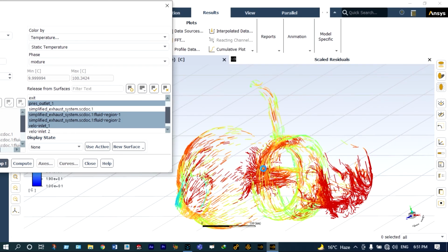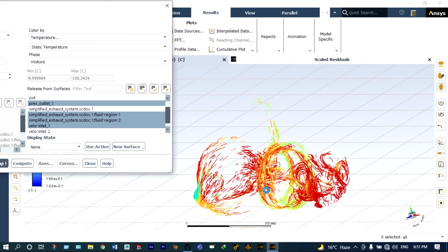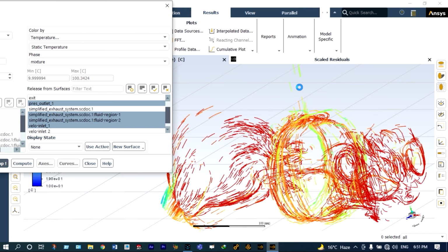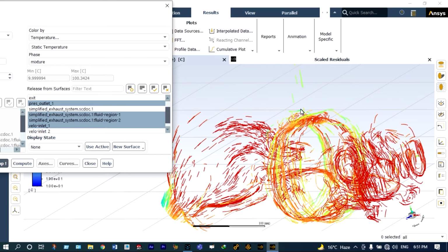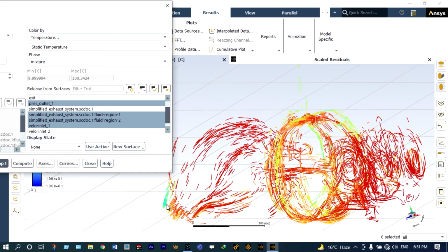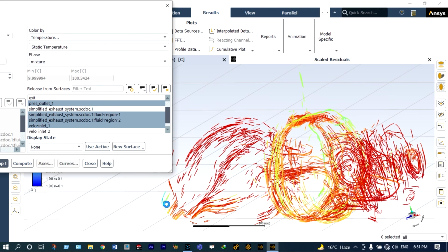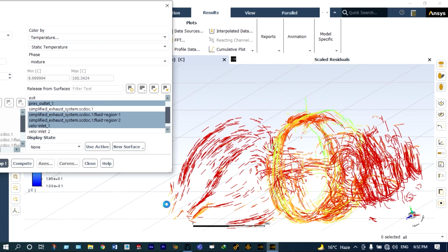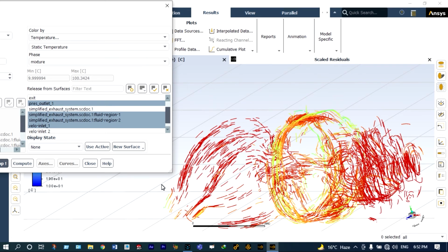It is showing the mixing of different fluids. From the right-hand side hot water is coming, and from the top entry we are forcing carbon tetrachloride, and that is being mixed at this location, and finally it is coming at the exit. At the exit location the temperature is in the range of 40 to 50 degrees centigrade, which is indicated by color. Okay, let us stop it.